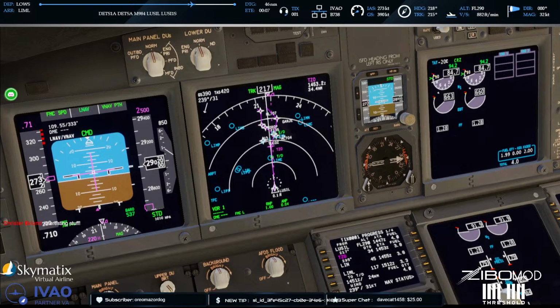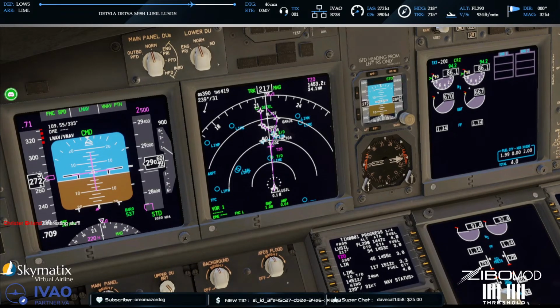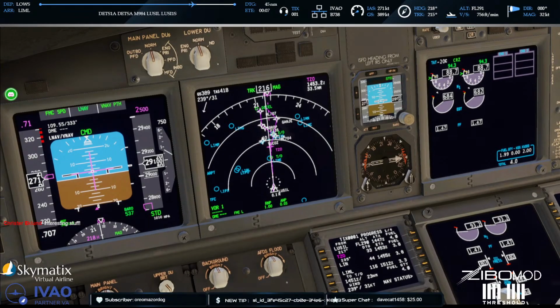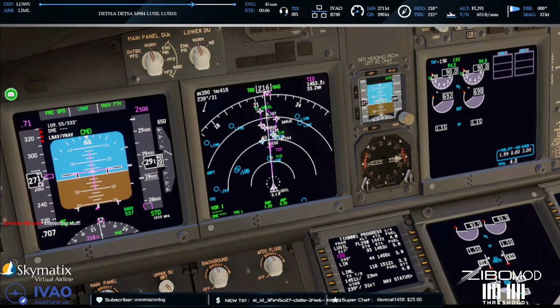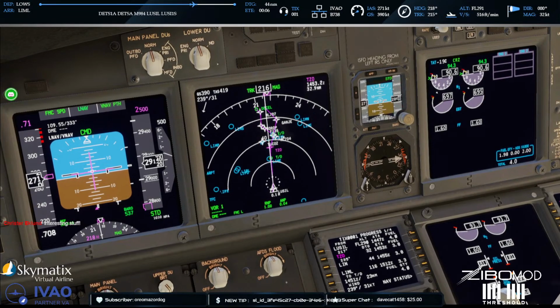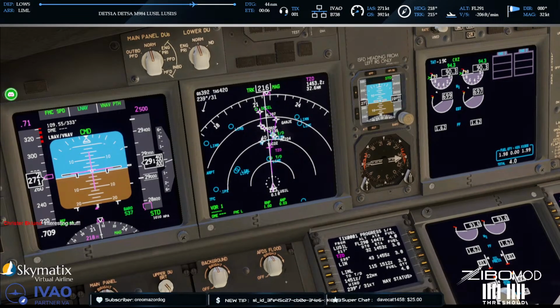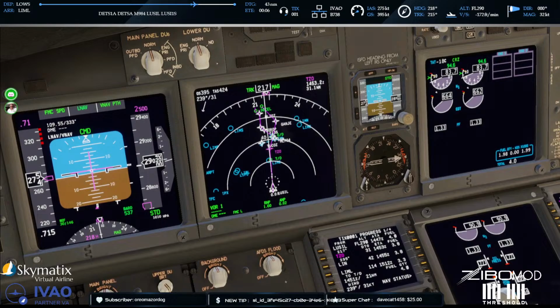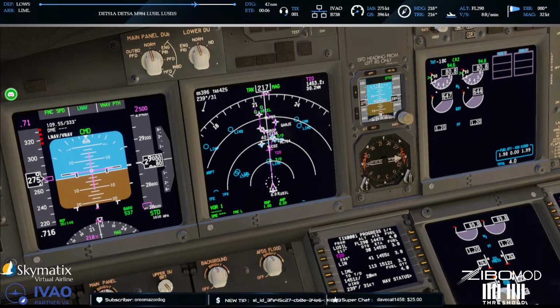And one of the reasons for the vast difference in RPM, think of the operating diameter of the fan blades, you know, the big bypass fan blades, and the diameter of the compressor blades. And if the fan blades were running at that same speed, the tips would be exceeding the speed of sound, so they have to be angled so that they run slower.